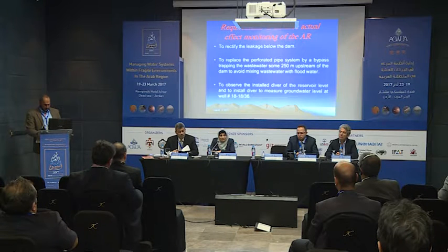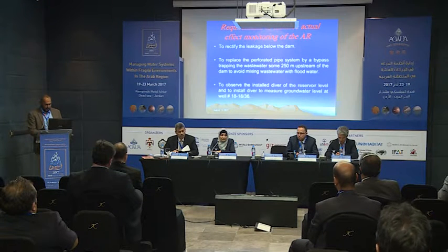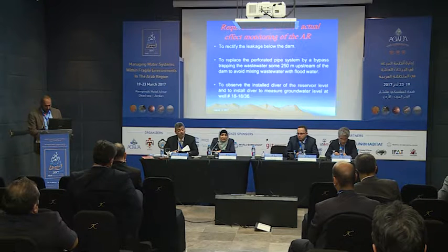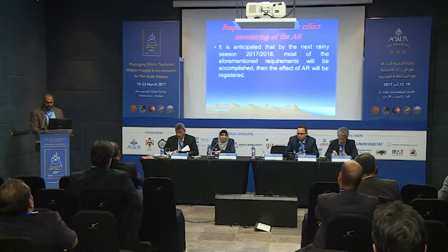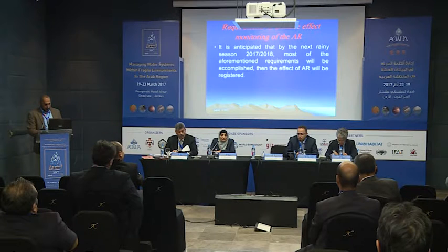Our recommendation after this presentation is to rectify the leakage below the dam and to replace the perforated pipes system by a bypass trapping the wastewater about 250 meters upstream of the dam to avoid any mixing of wastewater with flood water, and also to observe the installed diver of the reservoir level and to install a diver to measure groundwater level at the mentioned well. We anticipate seeing the effects of the dam of this project in the next rainy season, 2017 and 2018. Thank you very much.